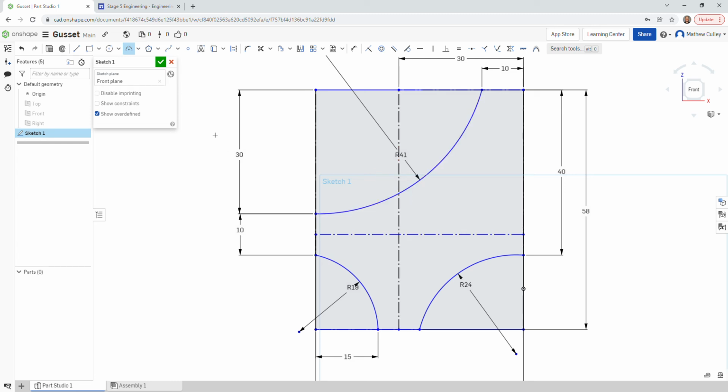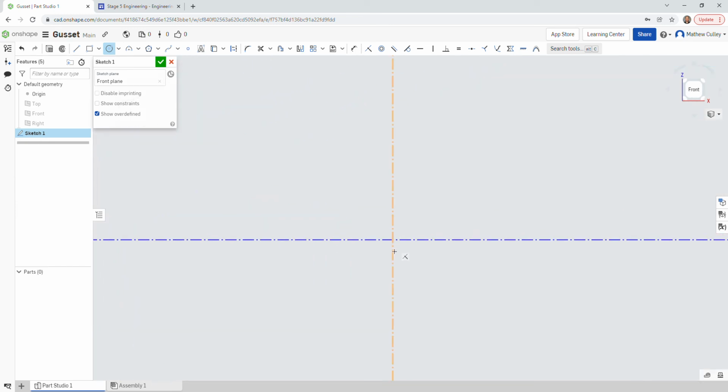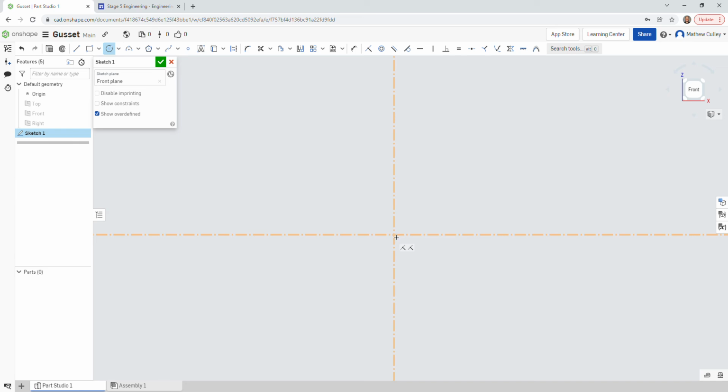Okay, what we might do now is we'll get in and we'll draw the circle, which is going to be the axle hole. So if I hit escape, okay, I come up to the top here and I select my center point circle, left click on that, and I zoom in on where these construction lines cross over. Zoom right in. Once both of those lines are highlighted, that means I've selected that point where they both cross over.